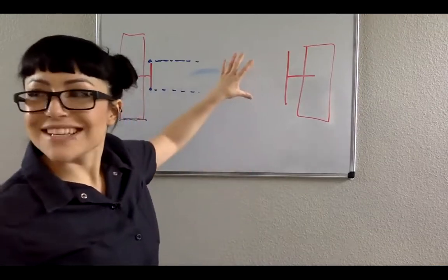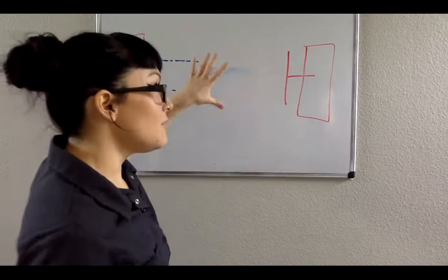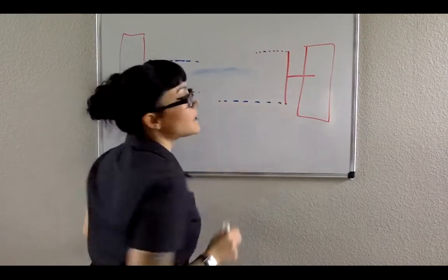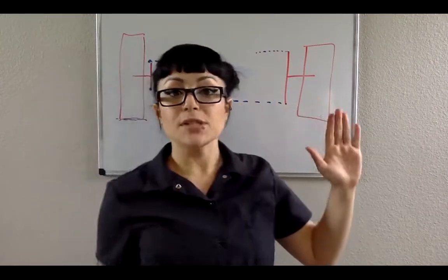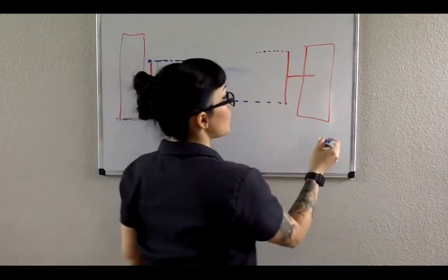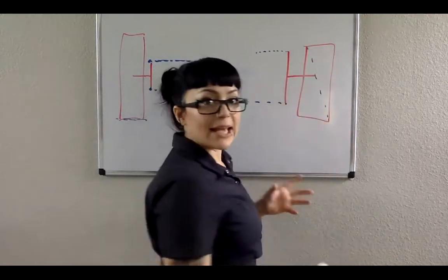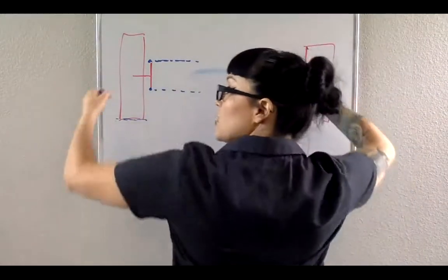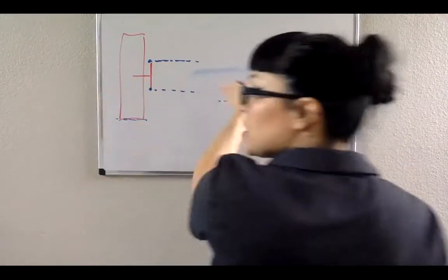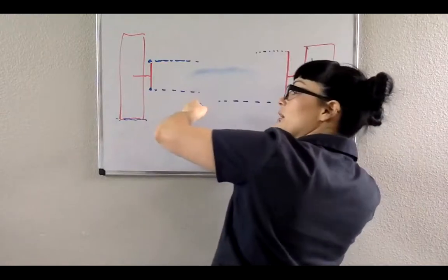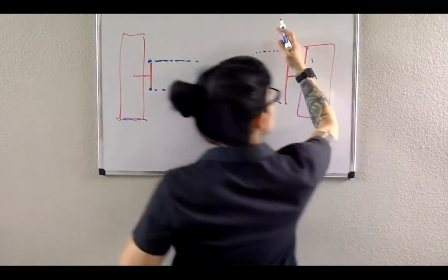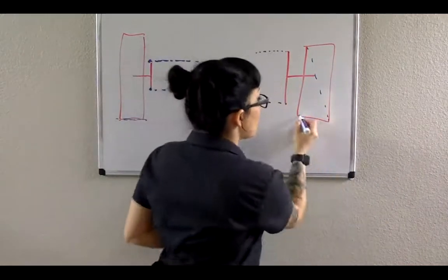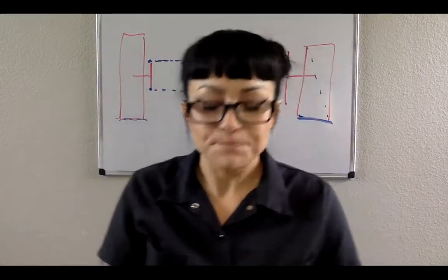What we did with our control arms, even non-modern stuff, is we've been changing the size of our control arms for a long time. A big advantage of a new design, which we call SLA, short and long arms, is that it actually helped the camber of this tire change and go more negative as the suspension gets compressed. That's a good thing, because as the vehicle leans over, say I'm making a left turn, my weight's going to transfer to that side. If I go negative as that weight transfers, it's going to sit the tire perfectly straight up, allowing our contact patch to be optimal.